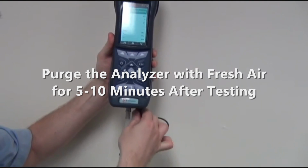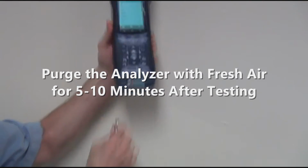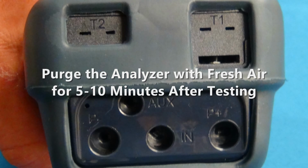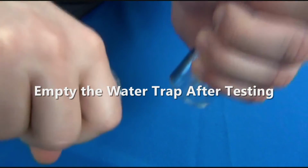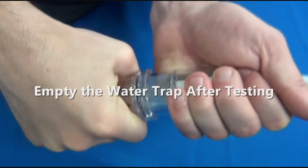When you are done operating the analyzer, let the pump run with all the water trap and hoses disconnected for at least 5 to 10 minutes to purge the analyzer with clean, dry air. Also empty the condensation from the water trap at the end of your test period.